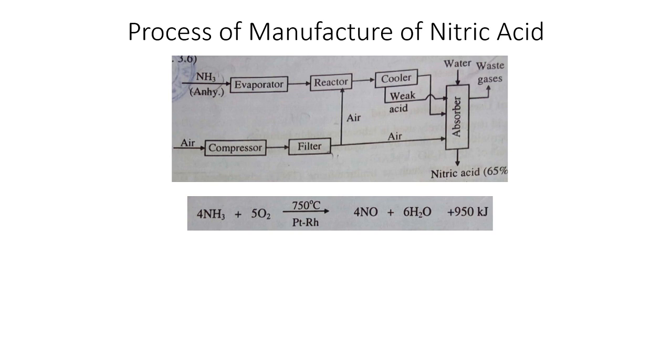So in the beginning you have to heat it, but after that, once the temperature reaches 800 degrees Celsius, the temperature is maintained by the heat of the reaction itself. It means you need not supply any energy, so you can stop the electrical heating, and this reaction helps itself toward further conversion of the reactants. So this is the reaction taking place in the reactor.